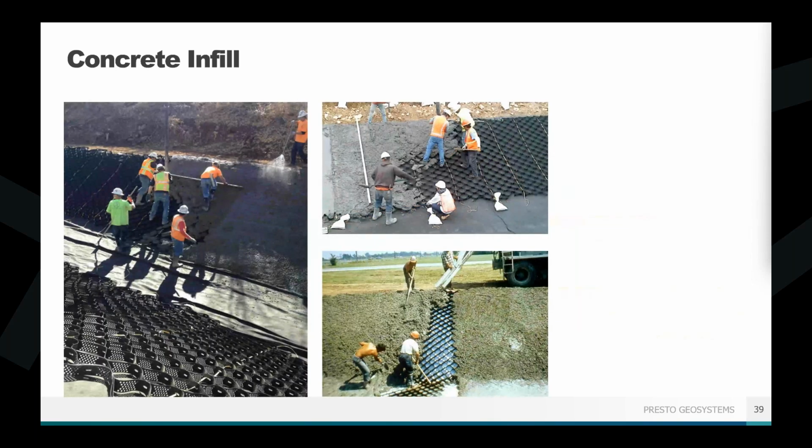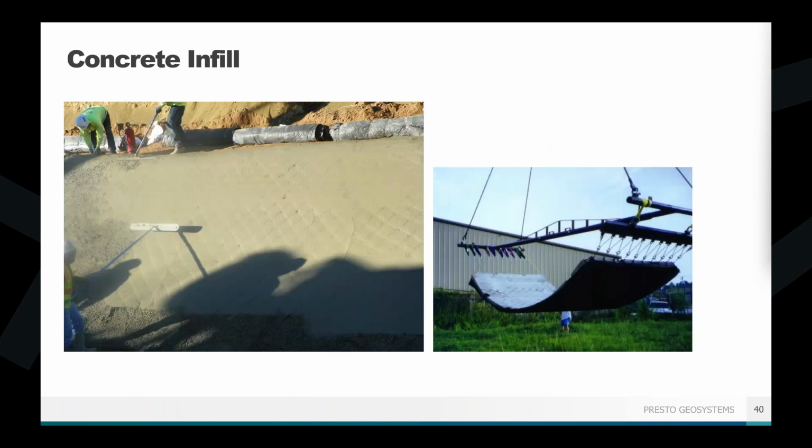And then as I mentioned, once it's anchored, the GEOWEB can actually just be poured. The concrete can be poured directly into the GEOWEB panels. So just take it directly from the concrete truck, pour it into the panels, drag it all down, make sure everything is nice and filled, screed it flush with the top of those panels, and you are good to go.